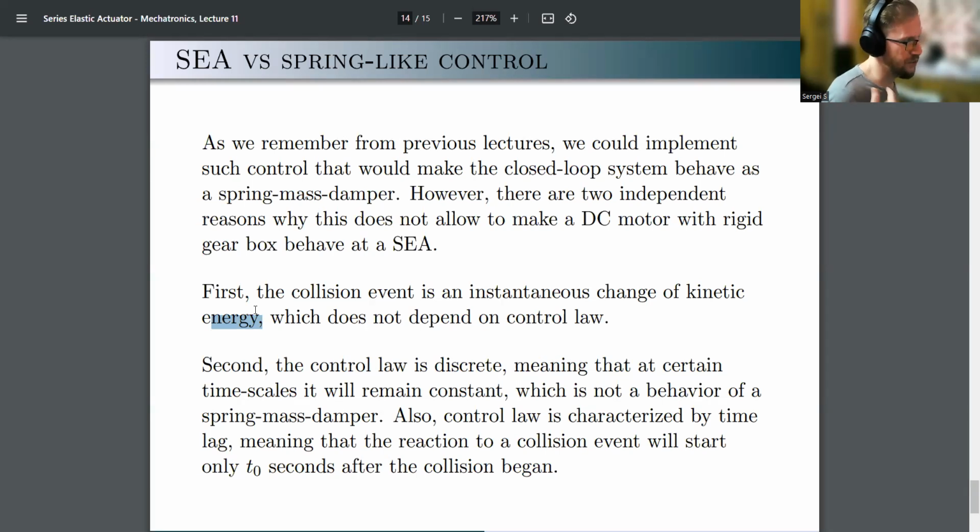But the internal parts of the series elastic actuator are not going to receive damage because there is no collision for them. For them, what happens is that the torsional spring slowly winds up, and potential energy increases, then decreases. There are other processes, but there is nothing instantaneous going on inside. So there would be no collisions inside.